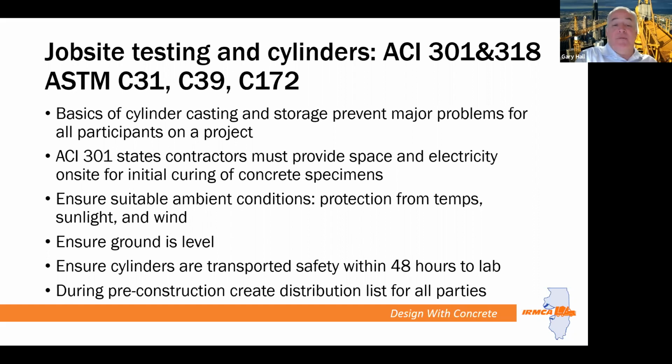Obviously ground level where your box is. And then once the cylinders are cured on the job site, we have to transport them to the lab within 48 hours. We also look for distribution lists for the ready mix producer and all parties on the job site.